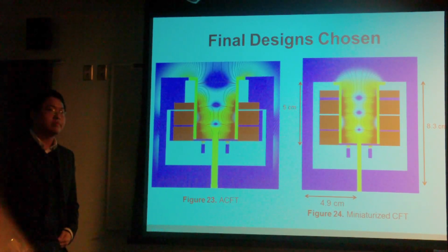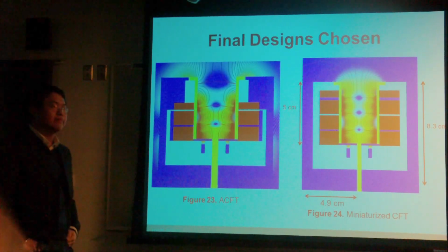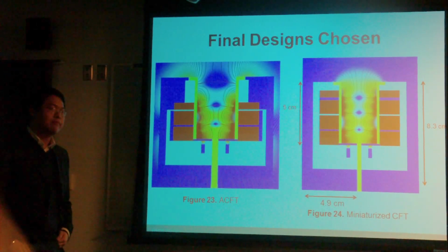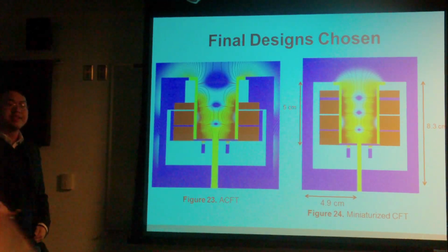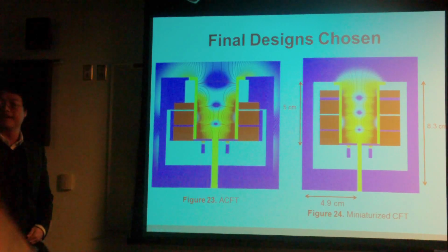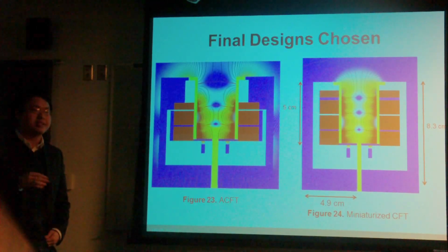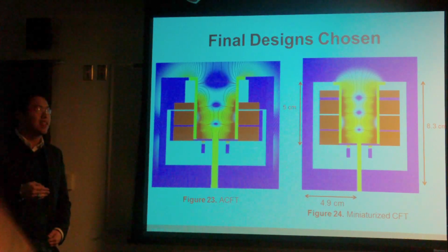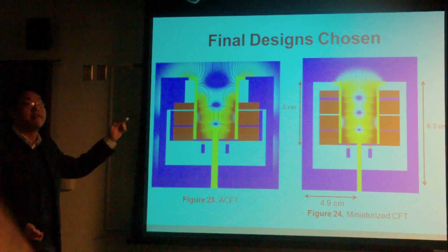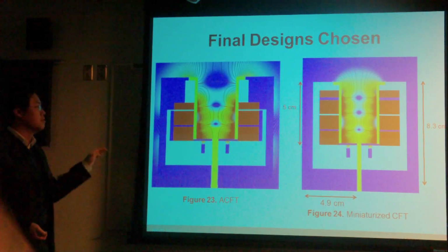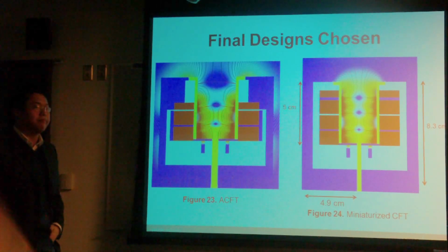Joe did something, yeah. So how difficult, when you're playing with these models, is it to get flat separatrices? It was fairly easy. Basically, I got some insight starting off from Steve actually. Having a smaller magnet at the exit would help focus the separatrix. So that is not that difficult. The only problem is that if you do that, then you drive the separatrix back from the mouth. And then you have the issue of possibly eroding the corners of the thruster as it comes out.